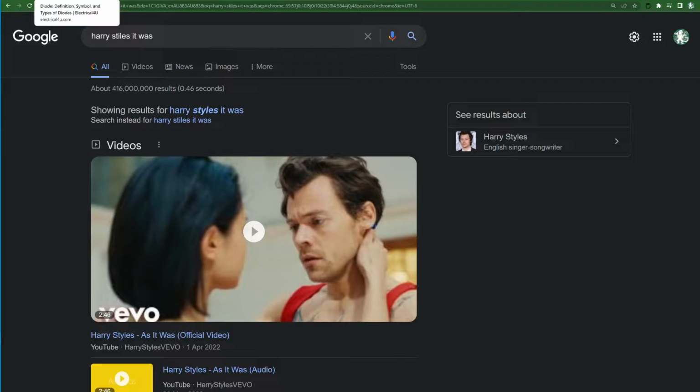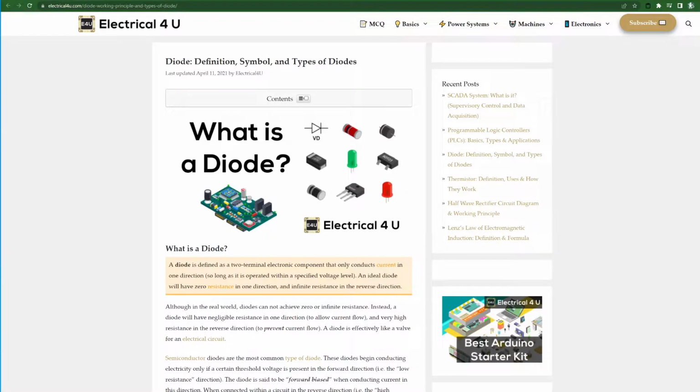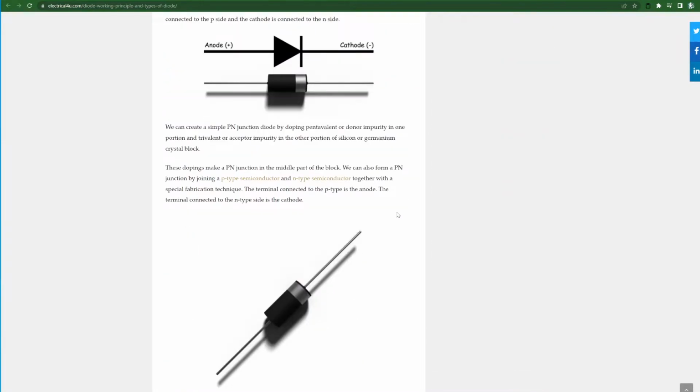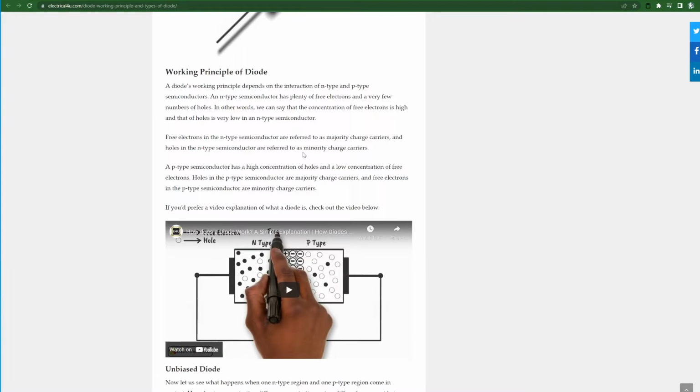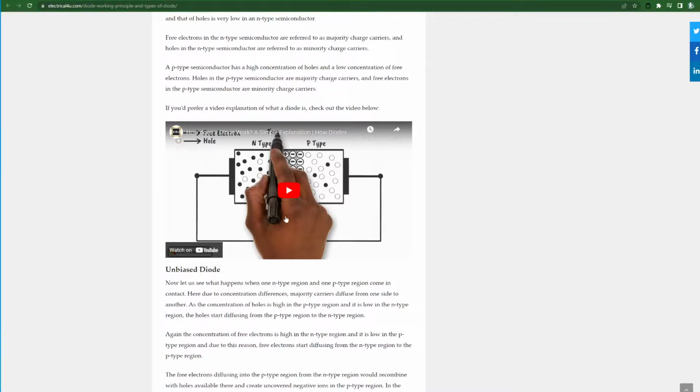So you go in one direction, yeah, diodes, that's what they do. You should know that at this point. Okay, what do you use diodes for? Well, there's a whole bunch of different kinds of diodes. The most famous is the LED. The symbol for the diode is a triangle with a line on it. If you buy a non-light emitting diode, it will have a band on the cathode side. We use them because they only allow electricity to flow in one direction.